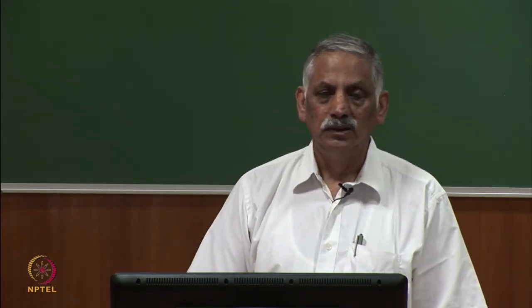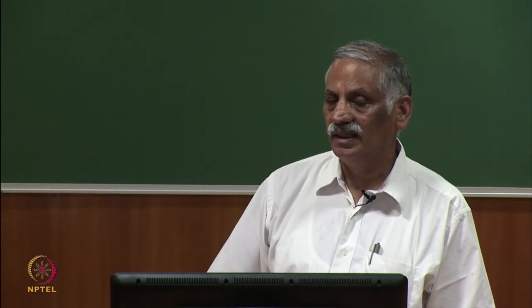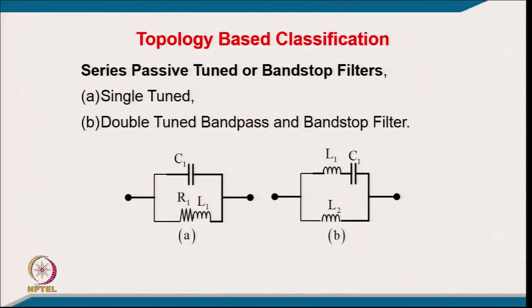One is it is disturbing the operation of the current fed load, because you are not allowing constant current to flow into the DC side, and another is it is disturbing the voltage across the current fed load. It is also inductive, that is also reactive. So, the reactive power burden further increases in current fed load, but in voltage fed load normally it is sometimes slightly leading reactive power, and this gives a lagging reactive power or inductive circuit. So, it matches the requirement of both separately.